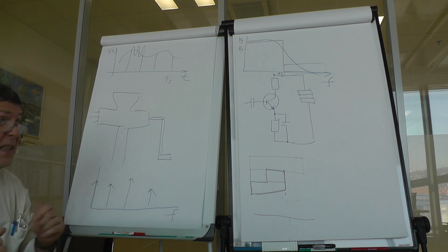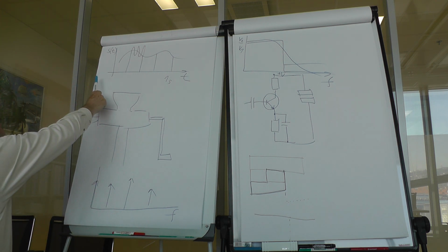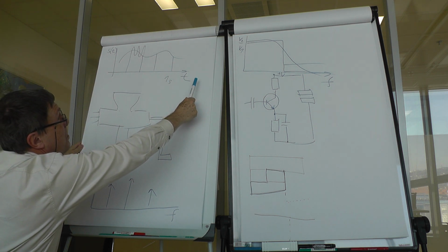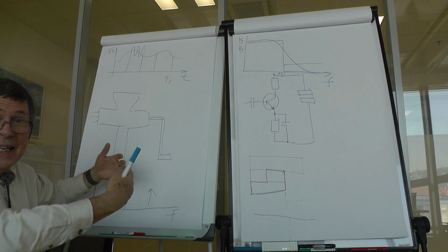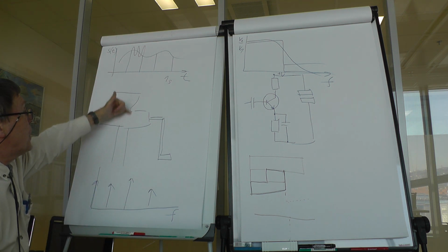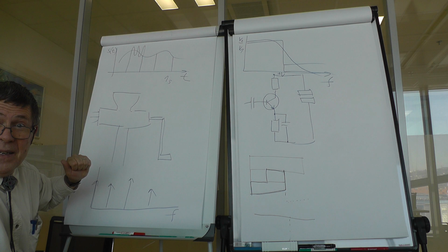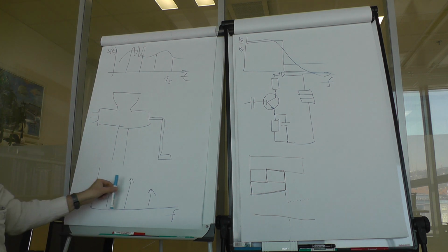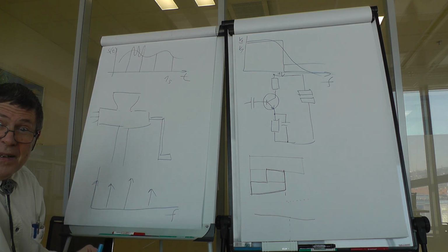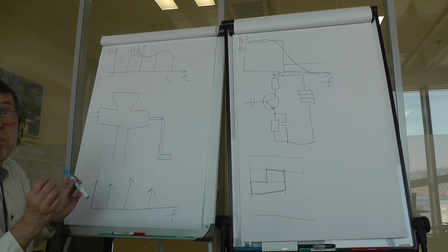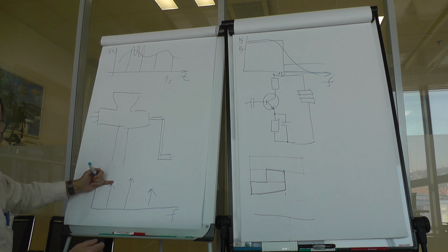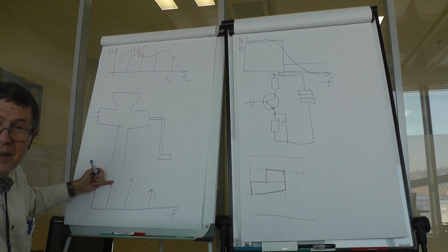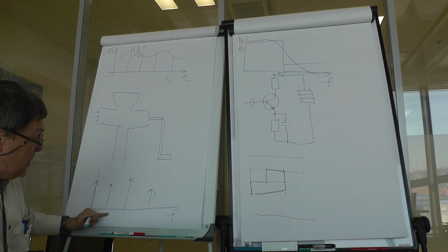It just means that if I do not know the period of the signal or the basic frequency of that signal, and I just blindly put it into a Fourier transform, then I get some frequency components. But unfortunately, it might happen that I have, say, 1 volt at 1 Hertz, but the reality could be anything from 0 to 2.